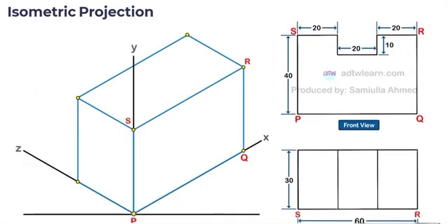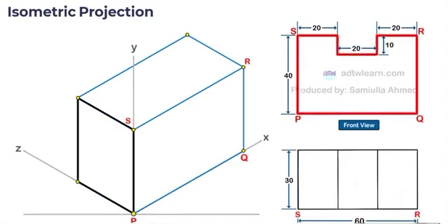Since there is no side view of the object provided in orthographic projections, that means there are no additional details visible from the side view. Therefore, we can darken these lines, because this is how it will look at the end. After this, we can start drawing the details visible in the front view. We need to draw this slot on the front view plane.